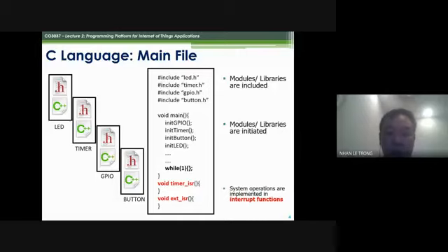Okay, you need to implement a kind of state machine. You can implement it in a timer interrupt because it is repeated, right? Like you declare a timer interrupt with the counter at 10 milliseconds. So everything in the timer interrupt service routine is gonna be executed every 10 milliseconds. So the behavior is very similar to while true, except that while true is forever and forever, and there is no delay.